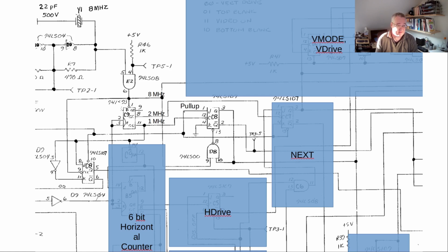You have to look at, there are a lot of signal lines that actually are driven by a pull-up resistor and don't have any kind of drivers attached. It makes sense to put them in a schematic, but sometimes you have to try to ignore them when you look at and try to understand that. So that's at the 1 megahertz clock. There is this pull-up on J, and K is 0. So if the 1 megahertz clock goes down, Q will always go up.